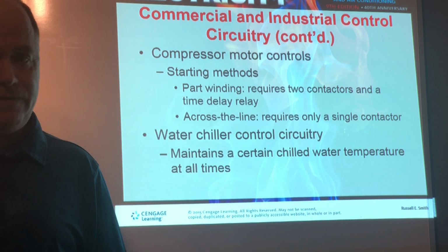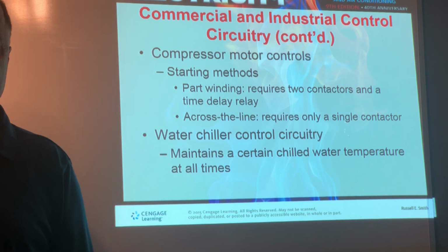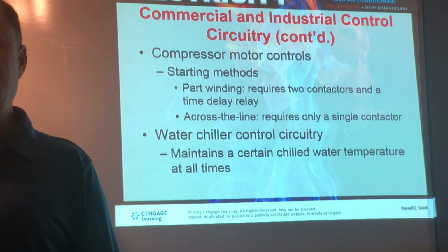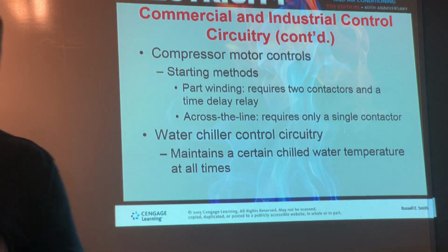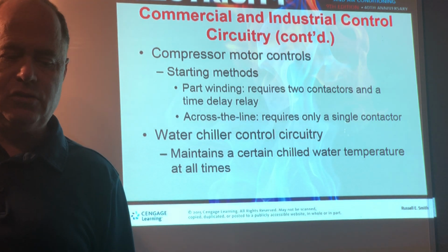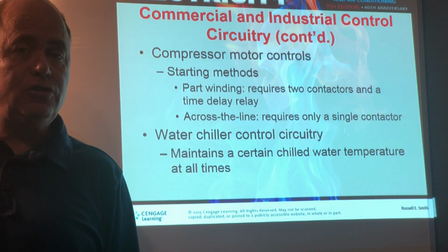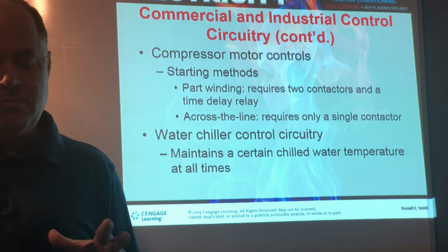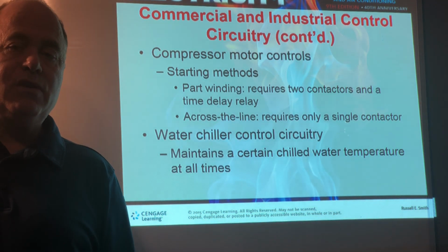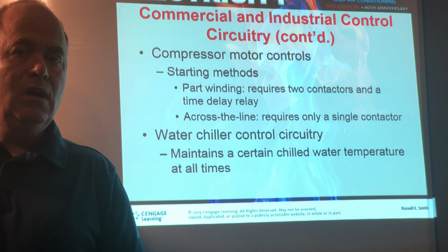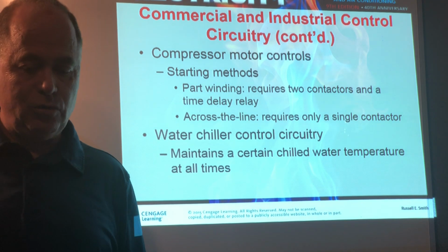And we have a lot of safeties, not just high pressure and low pressure cutouts, but freeze stats and things of this nature, and sophisticated magnetic overloads that are much quicker reacting than thermal overloads to protect our compressors. So more and more we have this advanced circuitry and a lot of communication to a central plant, to a computer that monitors everything and makes it easy to look at your problems and set your set points and schedules.